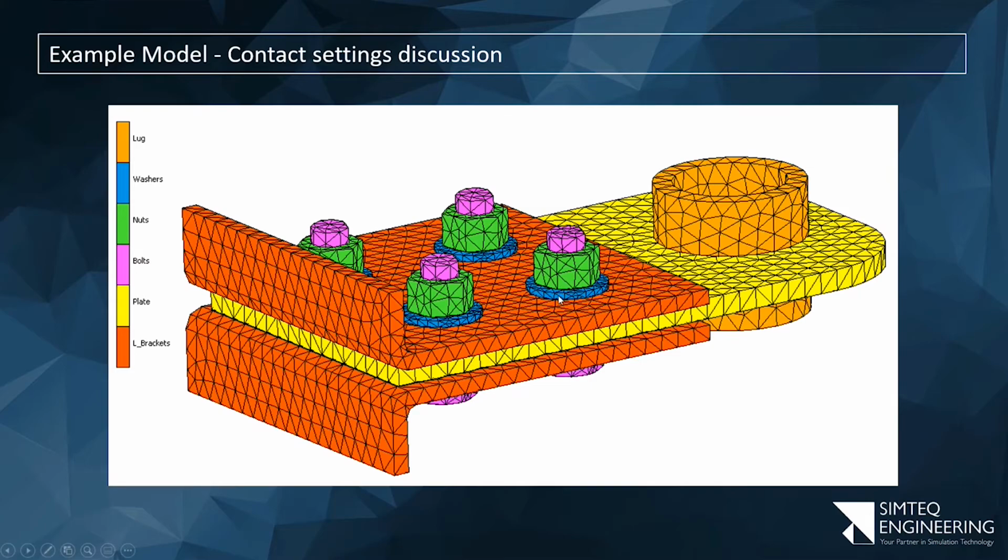If I look at these sections, for example, so let's say the washer to the plate, I'll just use project stress free, because chances of an overlap occurring is reasonable, not necessarily always, but in a lot of models we'll have that. So by using that, it'll move those nodes as needed perfectly onto that face, and the contact starts. If I look at the washer to this L bracket, in which direction should I make contact? From the blue to the red, or from the red to the blue? Okay, assume they're both steel. If it's both steel, then obviously from the blue to the red.